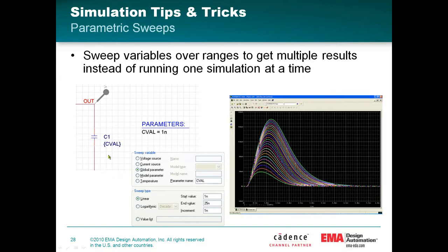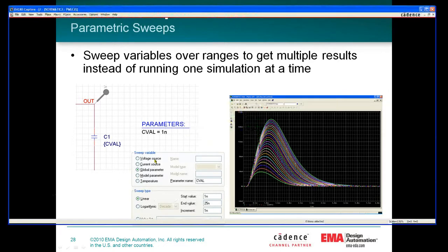So you assign that into the value field, and then you can create a parameter block from the special function. This is basically just a parts library that has a param block in it. Then create that variable in the parameter block and assign it a value. If you don't sweep it, it'll just use that parameter block to reference that particular value for that component. This also affords the ability to do a sweep, and I'll show you how quickly and easily that's done right now.